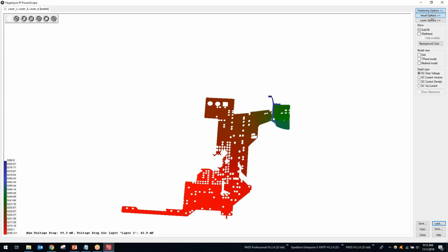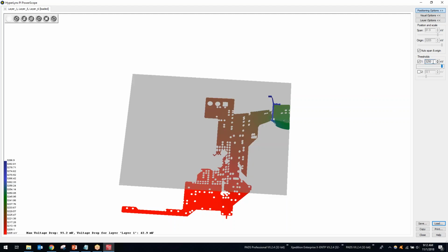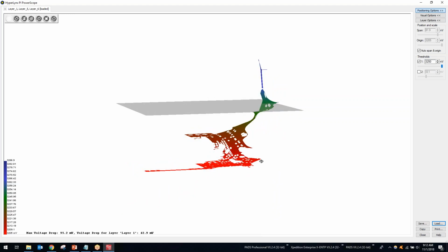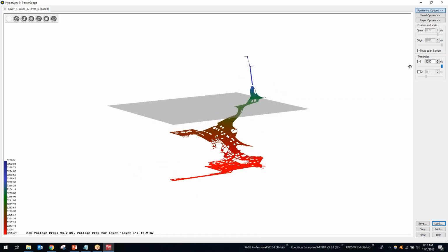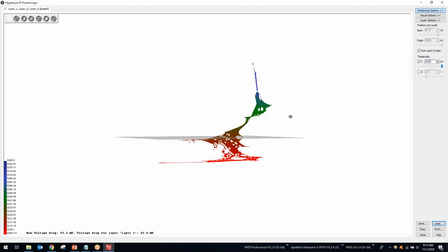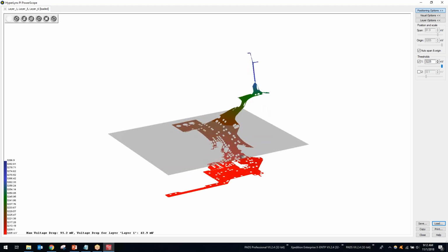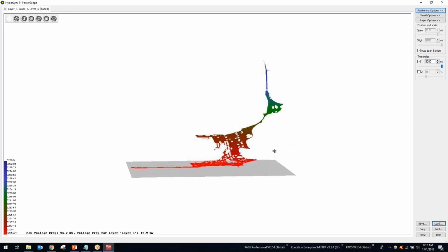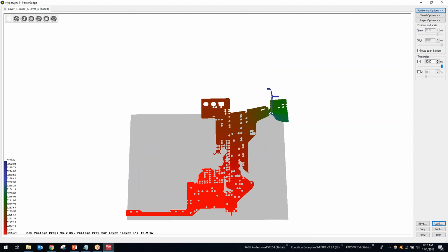There's a couple of different things I can do here. So that's DC drop. If I want to put in a threshold, let's say I want this to be no less than 50 millivolts of voltage drop, I type in 50 millivolts, and it's automatically going to place this little hovering icon showing that anywhere below this gray icon, we're going to have voltage drop issues. That might be a little too large, so I'll make this a 75 millivolt voltage drop. It looks pretty quiet for us. We defined in the constraints that we wanted just 100 millivolts of voltage drop, and if that's what we follow, it looks like we're passing the voltage drop simulation.